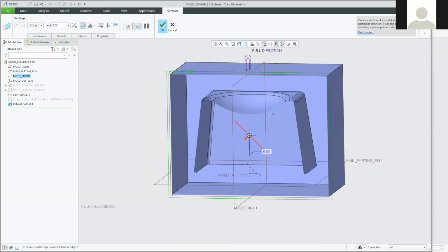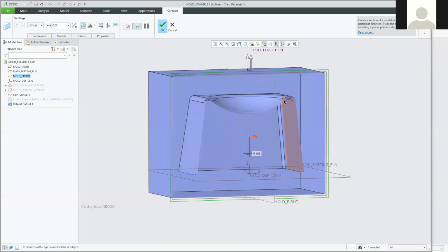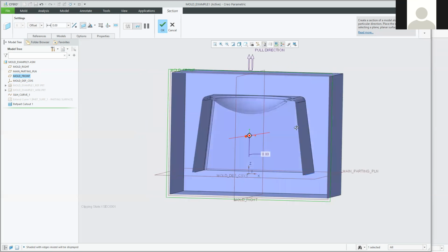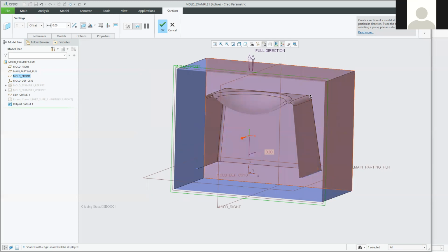So yeah, we're most of the way through this process. We blocked out where the gap in the center of this mold is going to be, where the molten material is going to be injected into. We defined roughly where this mold is going to split in half. We've defined the maximum external size of the mold itself. It's just that currently the mold is described as a hollow box formed by these surfaces. So we have to transition that into a solid block of material, or two solid blocks of material. One that represents one half of the mold and one that represents the other half of the mold.